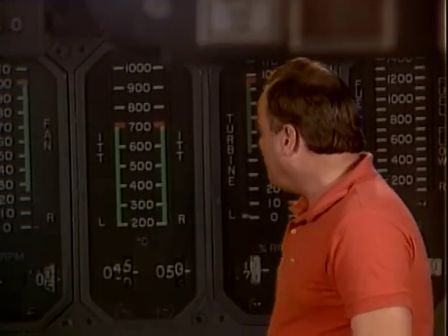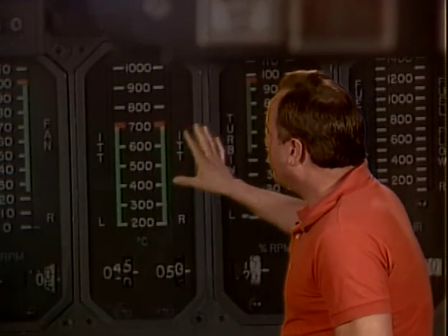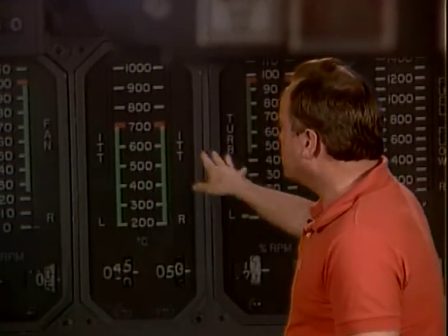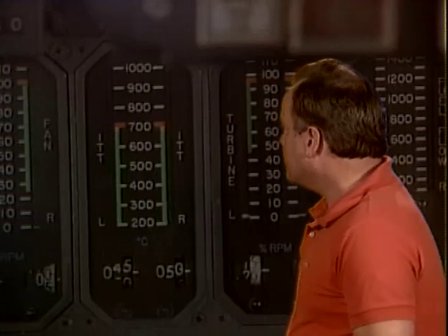All right, now sometimes they want you to know also that the engine could do more. You could put more power out of this engine than these markings will allow, and they're going to say, why is that? The reason is sometimes the airframe can't take all the power or thrust the engine can put out. So they're going to say that it's based on installed engine operating limits, which may not be exceeded, but that's not necessarily equal to the limits shown on the engine type certificate data sheets. The engine might be able to do more, but we're not going to let it do more because the power plant, or the airframe itself, might be a limitation.